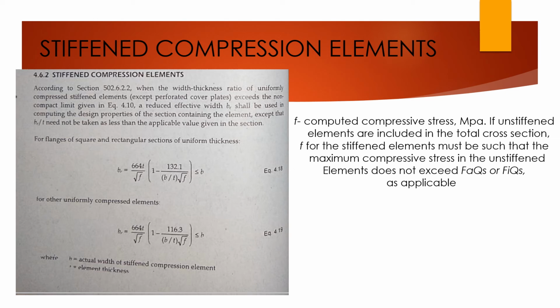Then if unstiffened elements are included in the total cross section, F for the stiffened elements must be such that the maximum compressive stress in the unstiffened element does not exceed FaQs or FbQs as applicable.